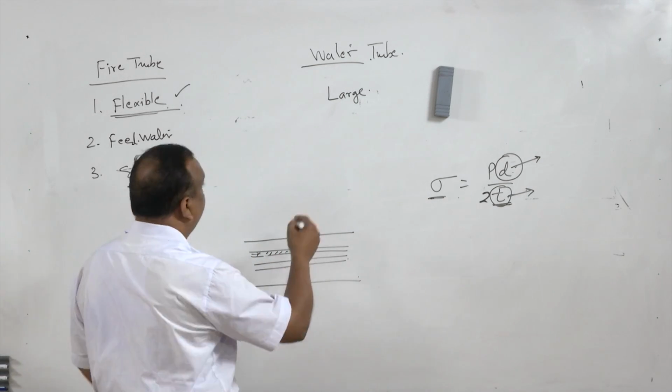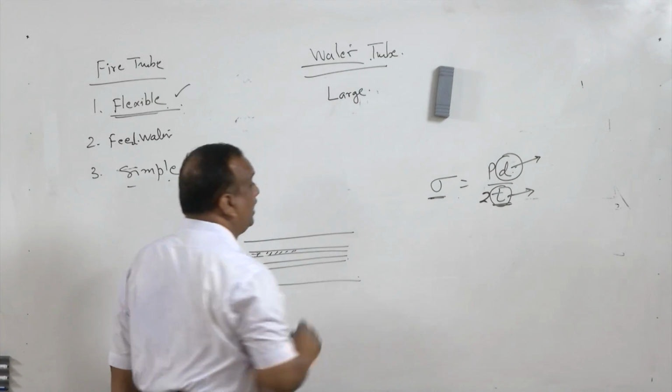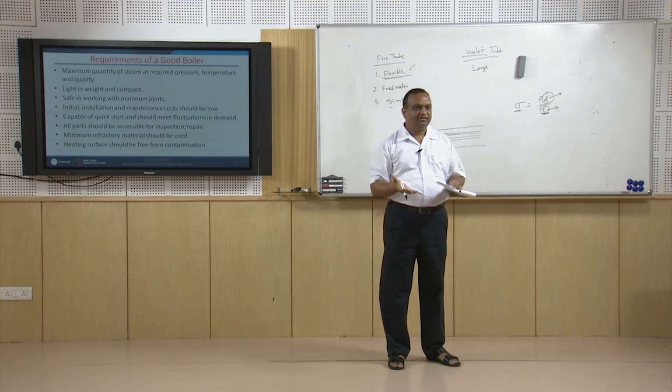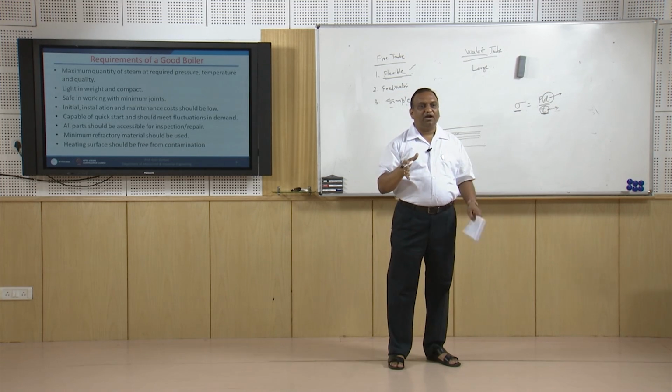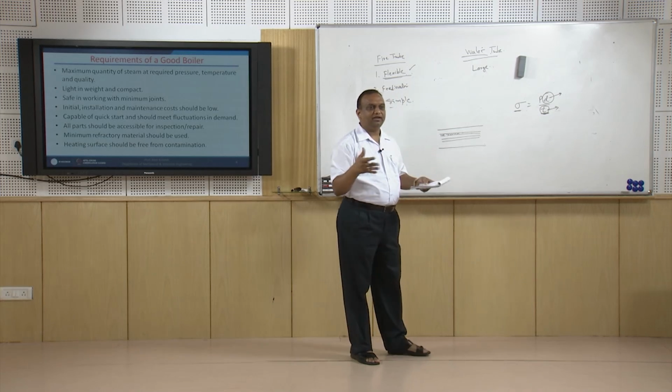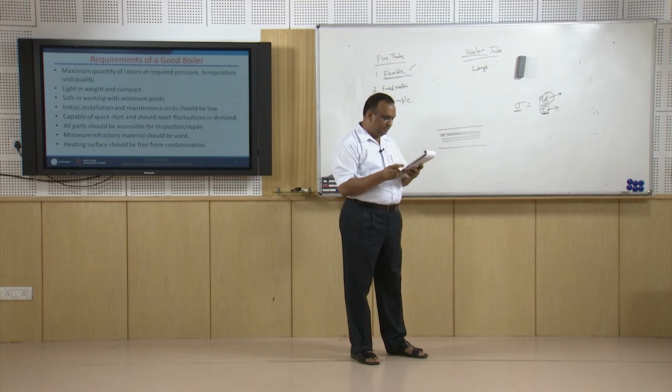And the second thing is, water tube boilers are easy to fabricate because the shell is not under pressure, right. So the main part which is under pressure is the tube of the boiler. So they are easy to fabricate, install and assemble at the site, right.